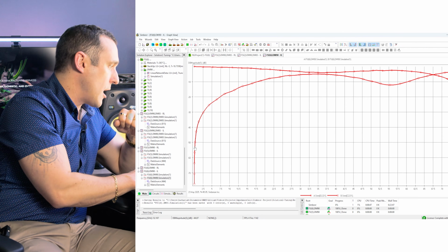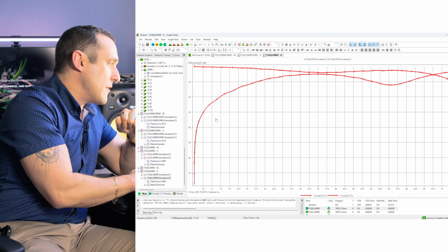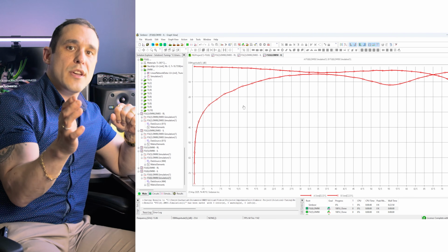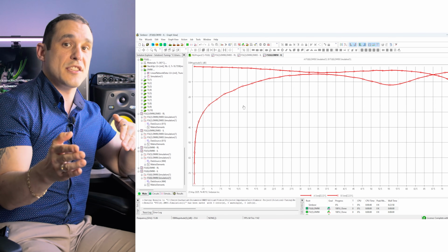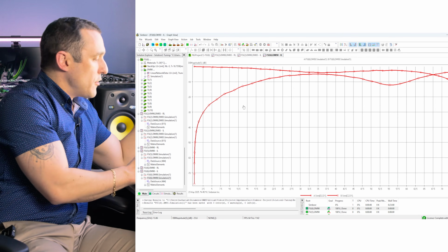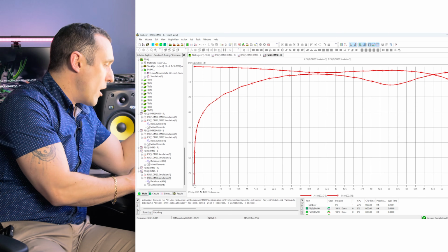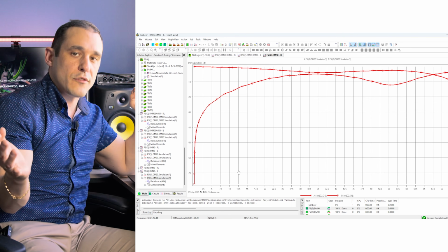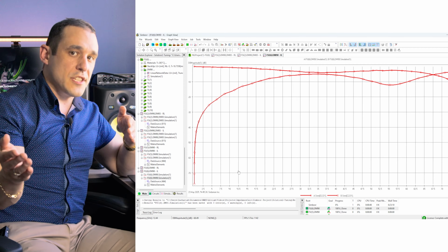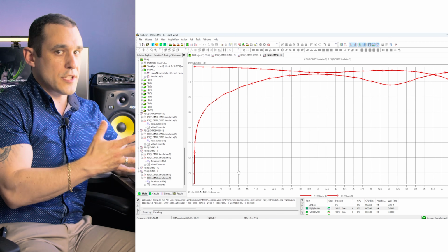And you can see here it comes up as this lower red curve. And so you can get an idea of just how much of that noise gets converted into common mode noise and at what frequencies this really starts to matter. So if you look down here below about 5 gigahertz and all the way down to about 1 gigahertz at the lower end, you get -70 dB of mode conversion.